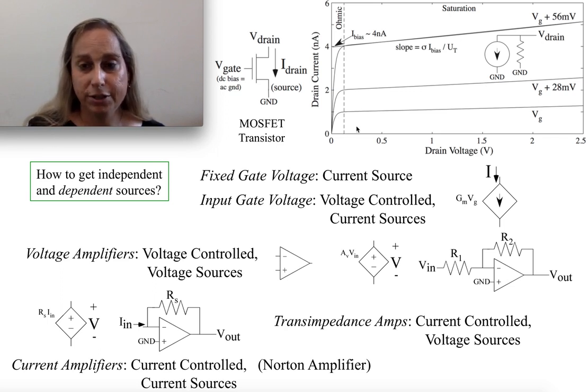Here would be such a set of measurements, where you would get something that starts off at 0, goes up to a particular potential, and then becomes fixed. This is for a MOSFET operating in subthreshold operation. This is what I get for one gate voltage, what I get for a second gate voltage, and a third gate voltage. And one of the things you notice is that it's relatively constant, at least in the view that we're seeing here.